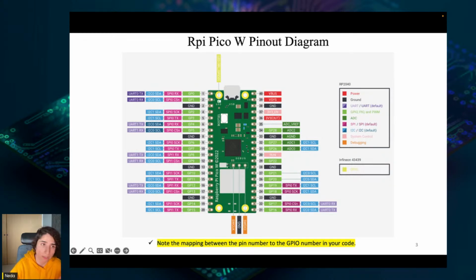Pin 1 is at the top left as you look at the board from above, with the micro USB port to the upper side, and pin 20 is at the bottom left here, and pin 21 the bottom right here, and pin 39 is one below the top right with the unlabeled pin 40 above it. So you can remember it very well from 1 to 40.